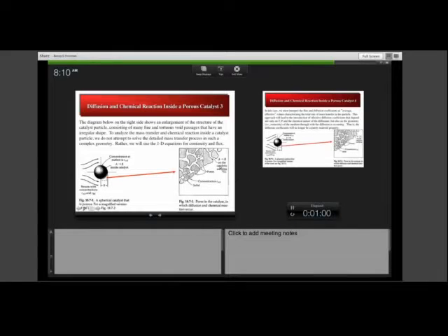Some of the gas diffuses into the particle where it undergoes a catalytic reaction into component B. B then diffuses back out of the particle into the gas phase, and that's the product that leaves the reactor. We're going to call the concentrations of A and B at the edge of the particle, at the particle surface, CAR and CBR. And those will be molar concentrations.